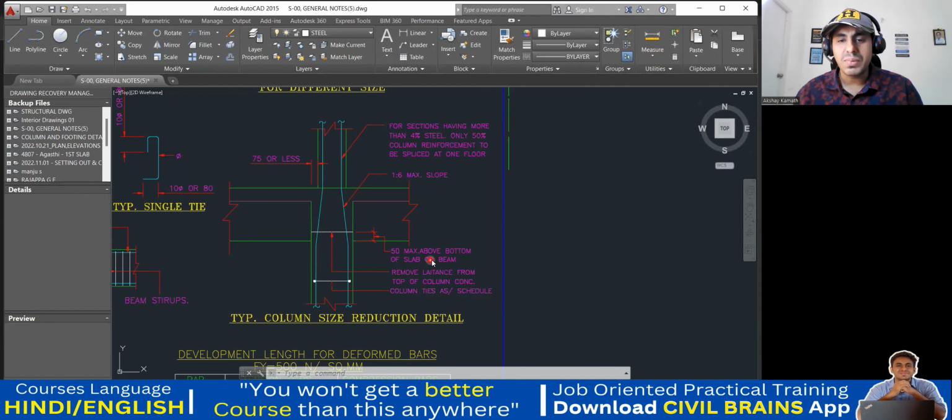So this is a 50 mm max above the bottom of the slab or beam. Remove the ties from the top of the column. Concrete column ties as scheduled. For sections having more than 4% steel, only 50% of the column reinforcement is to be spliced at one floor. This is what it is trying to give us. Okay, fine. So you understood the concept.